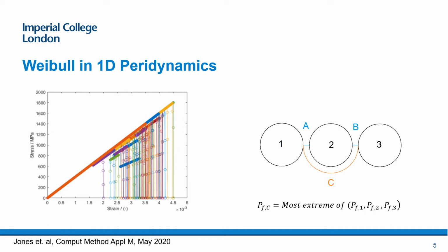So we found that this almost worked, but we did introduce this sort of slightly difficult problem where we would have tensile test specimens follow a normal stress strain curve until some point where a bond would break, and that would relieve some stress around the body, and then you would continue to accrue stress before finally fracturing. And we're not getting just a totally clean break, we're getting this sort of breaking in stages.